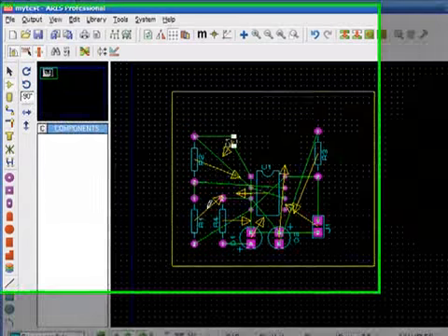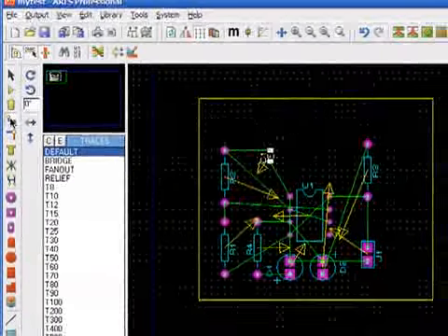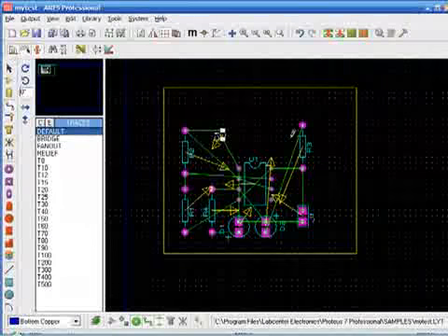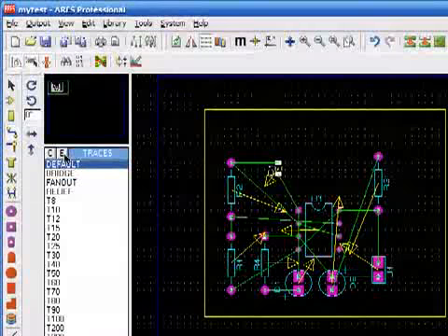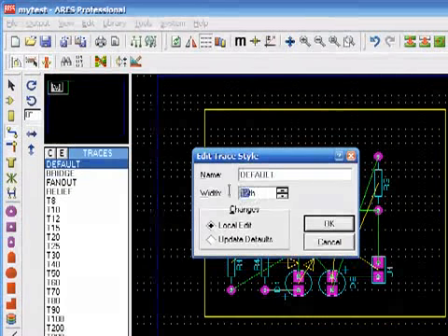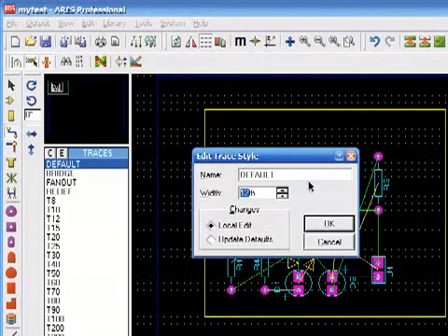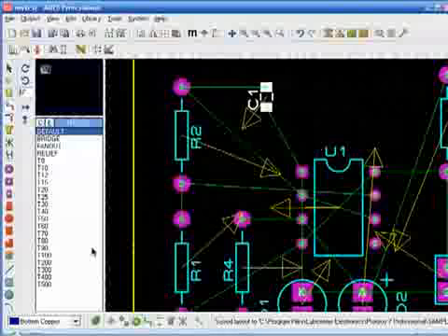So you have to now route the design. Here is the track mode. You can place the copper connections here. The default can be edited by clicking the edit button. It's quite useful. 12 width is normally too low for cheap PCBs. Make it 30 to 50 or even more if you like.